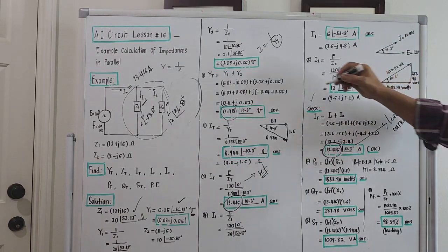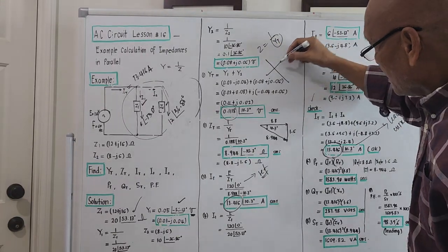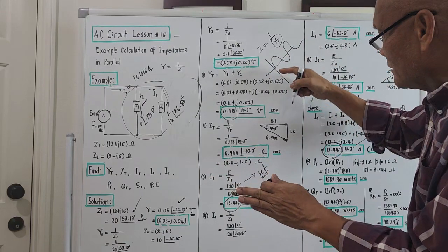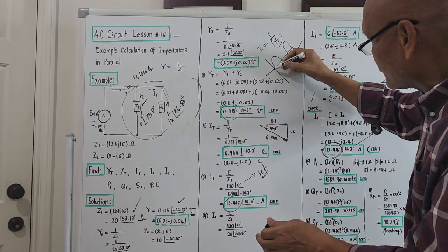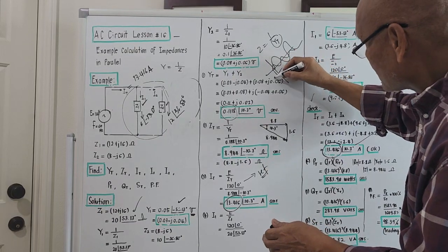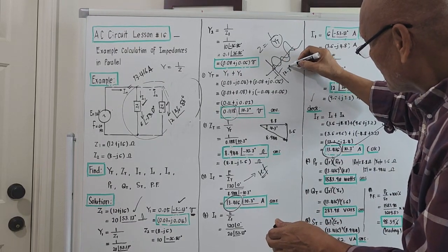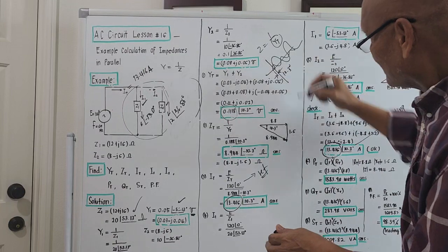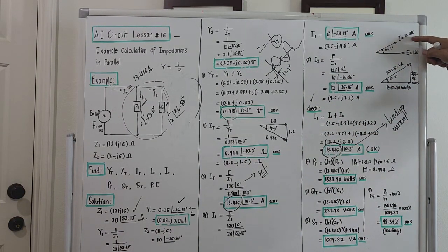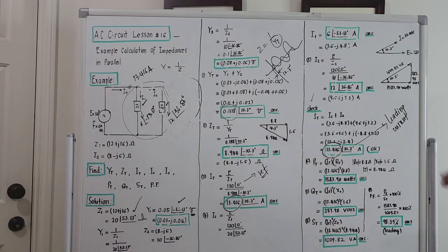So if you got the graph, if this should be the voltage, the current lags behind the applied voltage by 10.3 degrees, so it could be this one maybe. The angle of lag is 10.3 degrees, this one. Right? That's the meaning of this. Okay, the last part of the solution, it's an easy solution now.